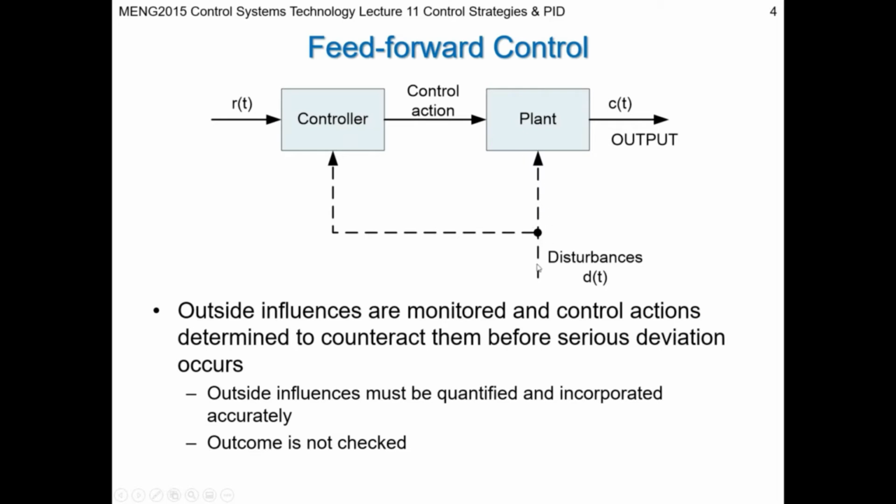Let's use an autopilot on an aircraft then, and you have sensors on the aircraft like airspeed sensors. If you're getting gusty conditions or a headwind, then you could actually detect what that disturbance is which is acting on the plant, and correct for it in advance by measuring it and adjusting your control action based on your measured disturbance. Right?